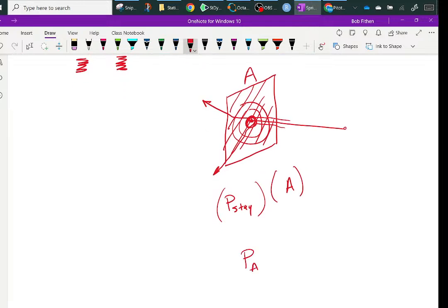That's just the atmospheric plus rho air v squared over 2. So you just put in 100 miles an hour, take the density, square that, add the atmospheric, multiply times the area, and that gets you the worst case scenario of the air pressure on that surface.